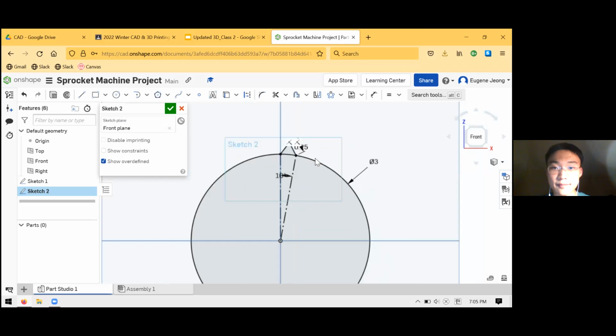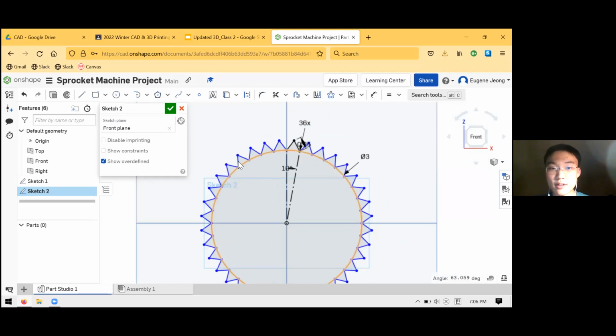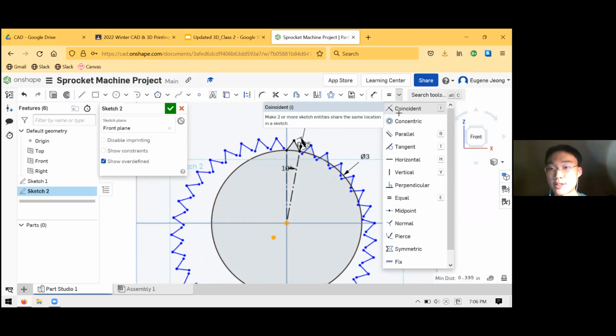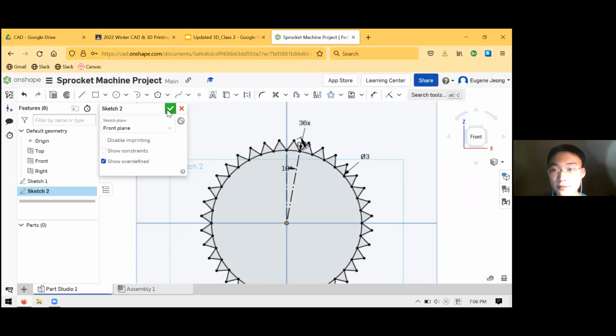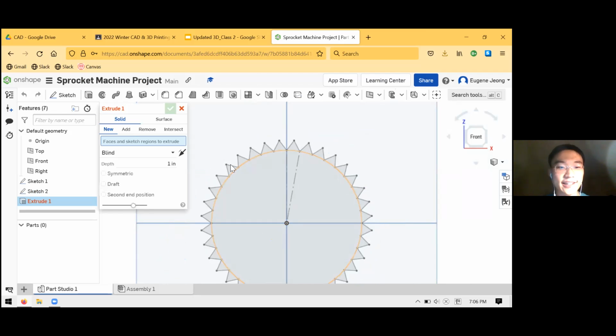All right, let me catch up real quick. And what you'll find when you extrude, you recall that whenever we had multiple sketch profiles to choose from, when you're selecting your sketch regions for your extrude feature, you have to click every single one of those triangles. And that's kind of not what we're going for here. We're trying to do things fast and quickly.